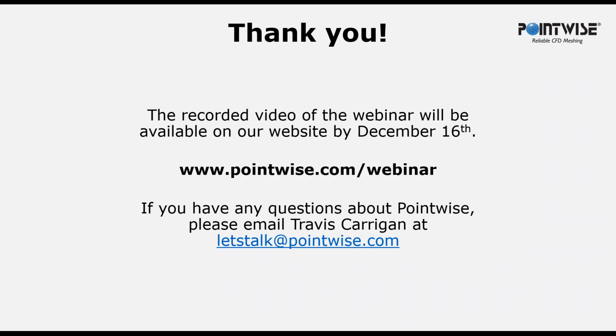So it helps to go into a mode, make all the changes that you want to make, and then apply them. That can save you considerable time. So if you're going to change many spacing constraints, use grid distribute instead to perform that function. If you just want to do one or two, just one-off spacing constraint changes, use the toolbar.